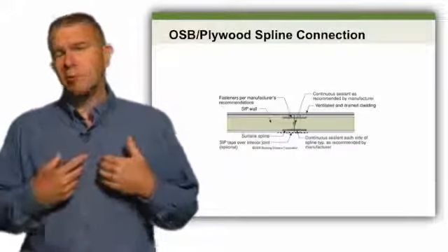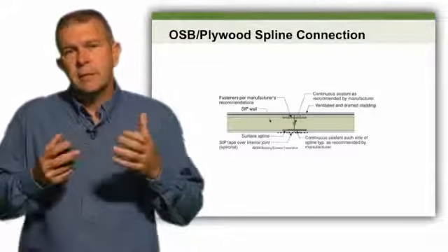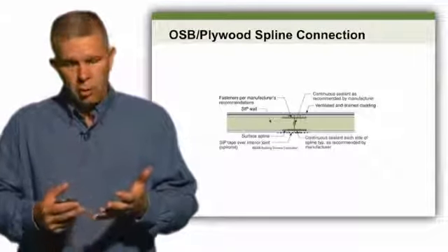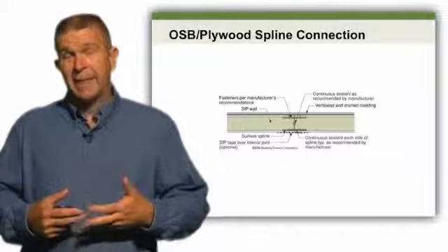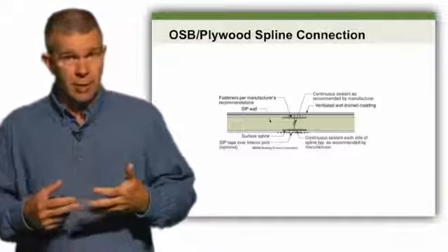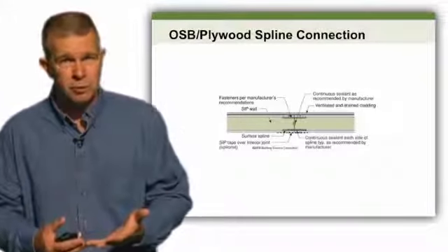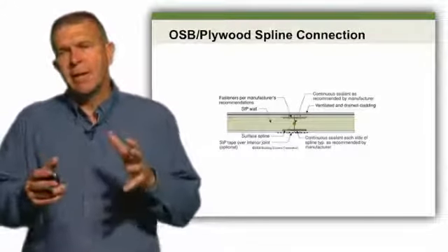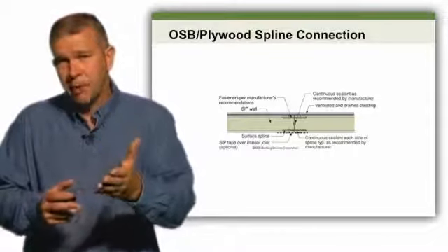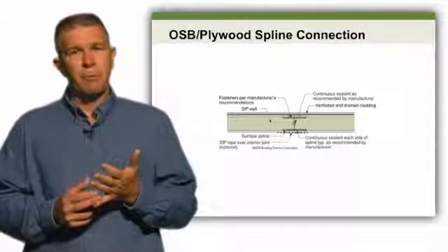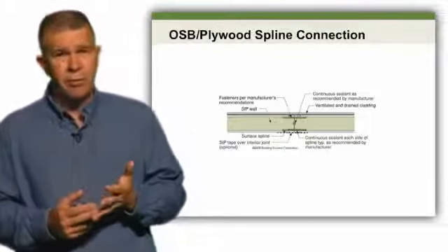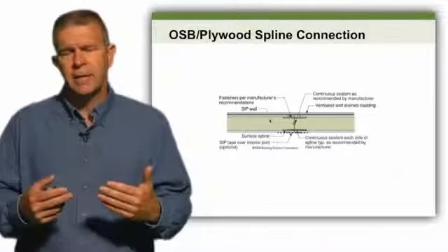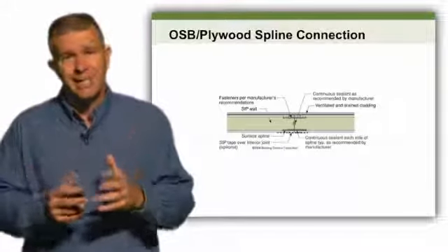So from a design perspective, this detail means that we're not incorporating additional wood. We're not, from an engineering perspective, asking the panel to do more than it can do and therefore having to add wood or additional support to the system. We're letting the panel do all the work. So this detail is very nice, and also from your perspective as a builder, it means you can put up the system faster. You don't have wood for thermal bridging, so it becomes more energy efficient. It's a speed issue. It's a cost issue. It's a great detail to incorporate into your design.